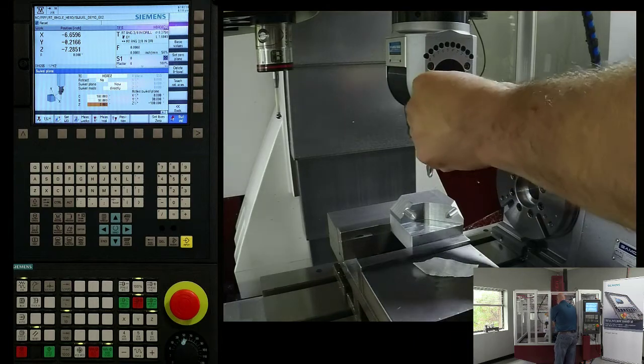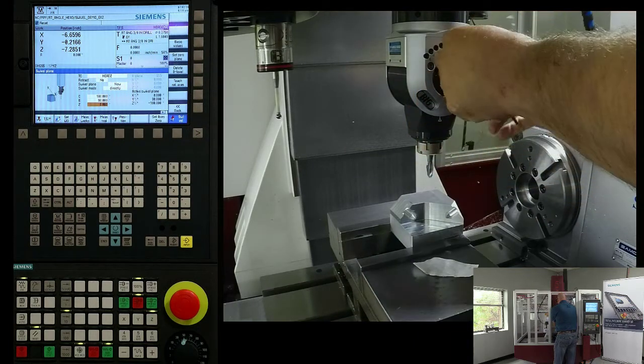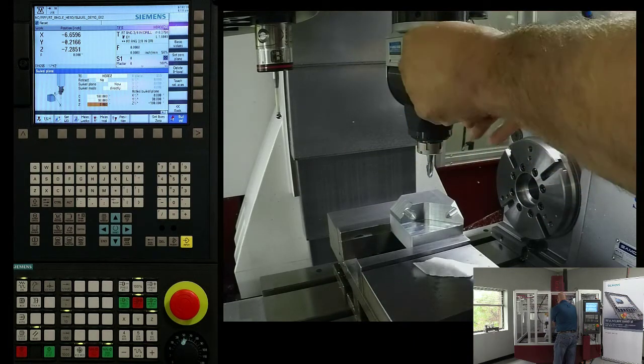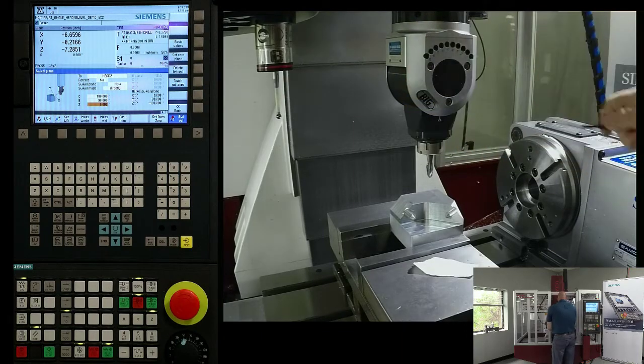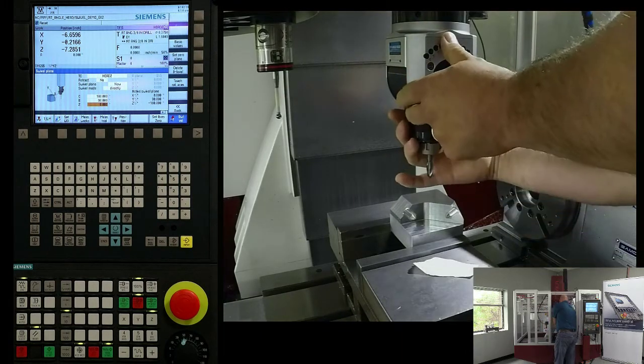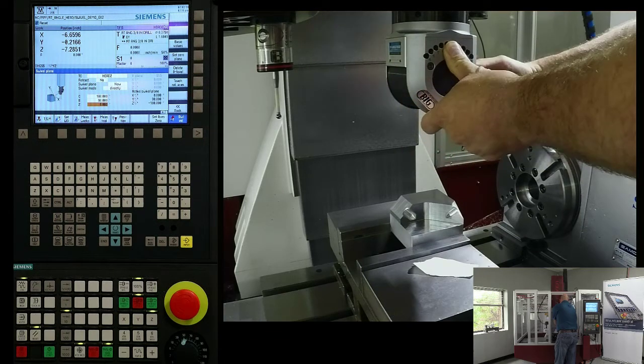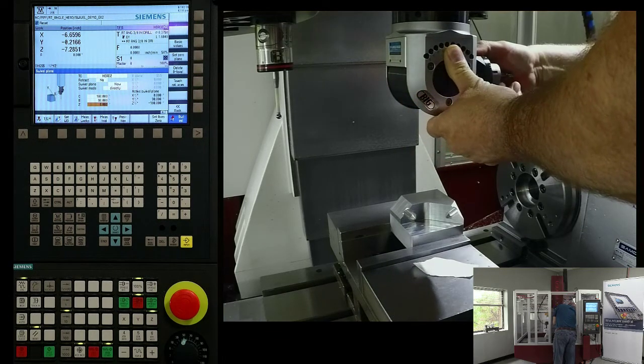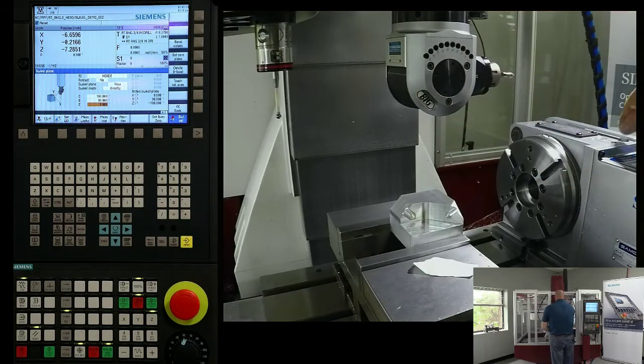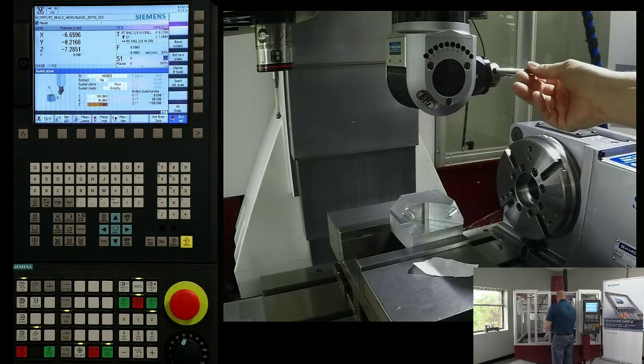Okay, so we'll loosen up our bolts. If I was only worried about getting this within a degree increment, then I would do exactly what I'm doing. If I start moving around the rotary, then you may want to actually indicate in the physical unit by, again, putting a dowel pin, something like these, chucked in.